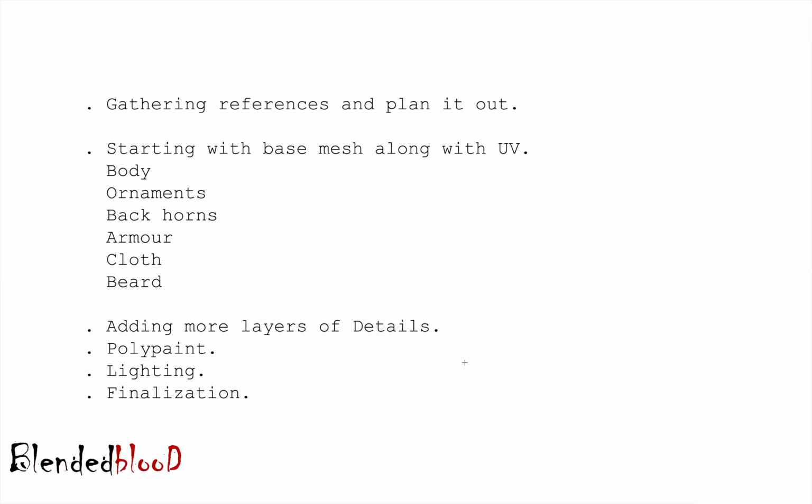So what kind of topics am I going to cover during this whole lecture? First of all, gathering reference and planning it out, and what kind of reference I was using during this process. Then starting with the base mesh along with UV, because what I was trying to do, I was making the base mesh in Maya. At the same time I unwrapped the whole model, then exported it to OBJ and imported it to ZBrush for further detail.